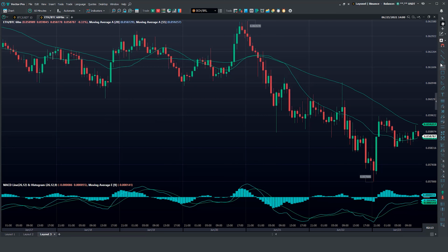We must pay attention to the very important setting of the studies. In the Studies bar, under Studies and Layouts, you can choose whether you want the study to be plotted for all layouts or only for that specific layout. So, if you select the option for just that layout, it will draw resistance or some other study, and that study will be only visible for the given layout.